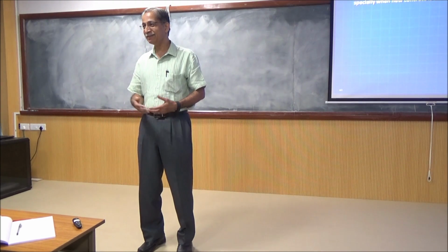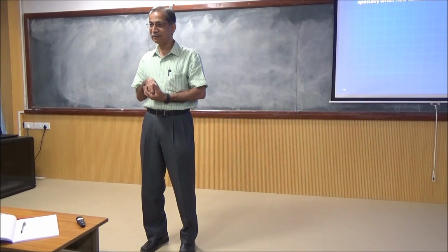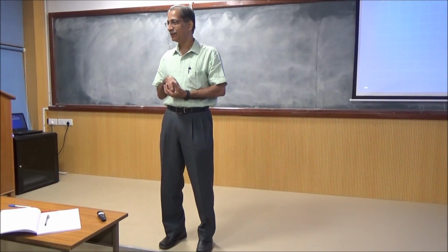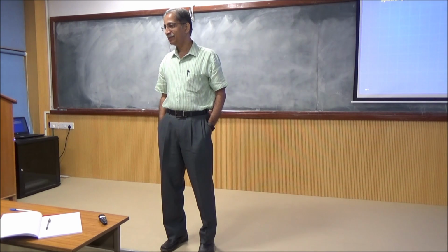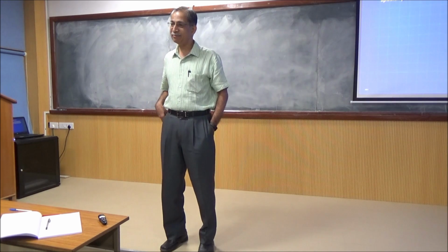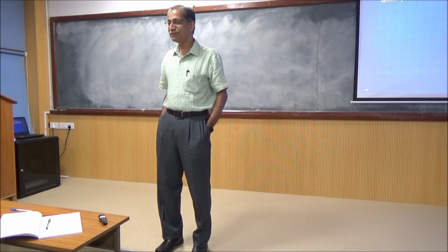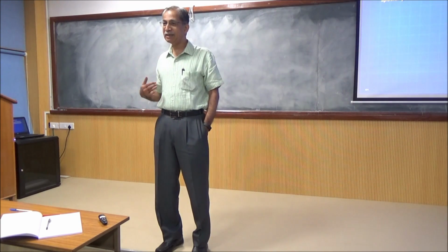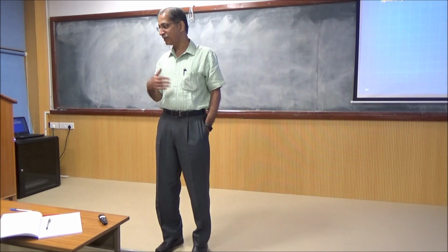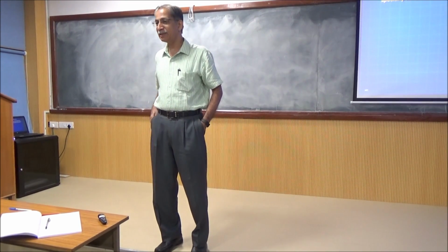I said, I'm sorry, because your structure is sitting on a concrete pedestal. That pedestal is going to shrink. And that distance may get affected. We solved the problem. It was very interesting, very challenging. But there are all kinds of cases, so it depends on the level of accuracy. But shrinkage can cause problems. The next is, how do you analyze for shrinkage?